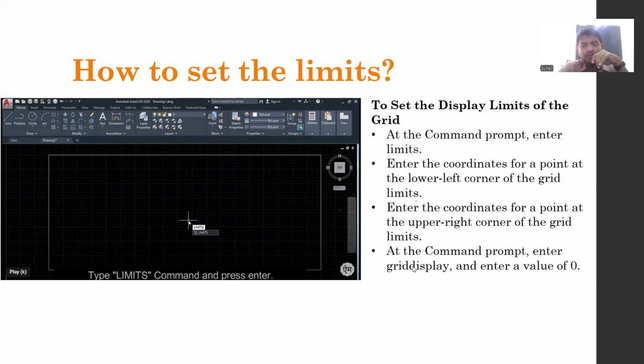So this is a way of doing it. After doing that, I will explain: you have to click Z, enter, and A, enter, the zoom all option. After that, you have to click O, then enter. Then you can find the overall display of your limited area. I will show you, okay? Don't get confused about everything. I will show you and I will explain.